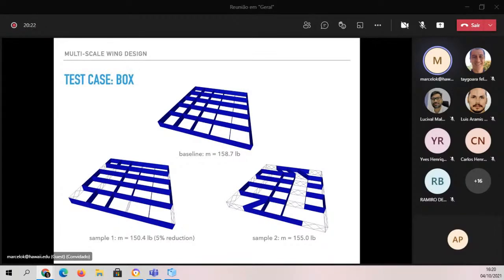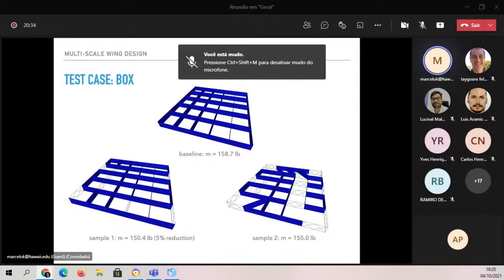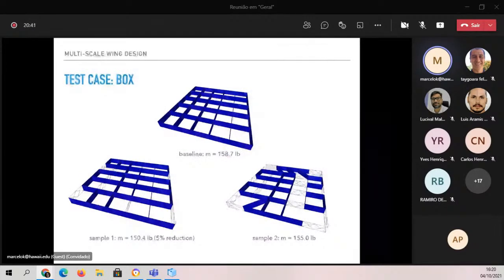But what is interesting here is that we can have any layout, as you remember from the instructions, but the X layout was chosen. So of all layouts that were possible, the X was chosen. And it makes sense, because the main purpose of having those members, spars and ribs, is to carry shear, and to carry shear the X truss is a good design.